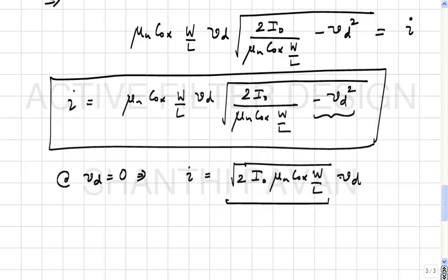Okay, this makes sense because this is what you would get from small signal analysis. But if you extrapolate small signal analysis without thinking carefully, then you would conclude that regardless of how large a Vd I put, I would get this Gm times Vd, which is not correct. The large signal expression here is telling you that as Vd starts to become large enough, the party is soon over, right? Because what happens? This factor goes on increasing or decreasing. As the magnitude of Vd goes on increasing, this factor under the square root will eventually reach 0, correct? Which is telling you that the transconductance is whatever it is.